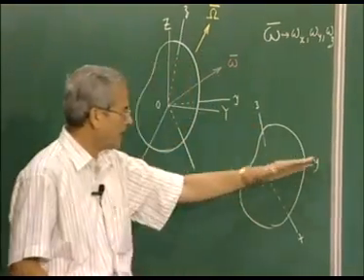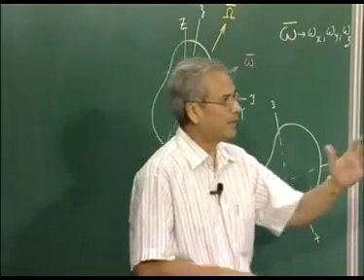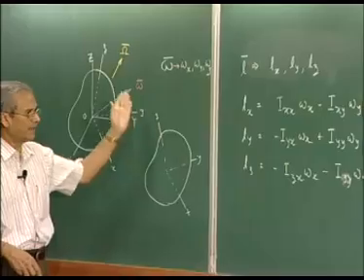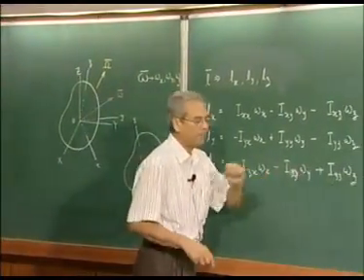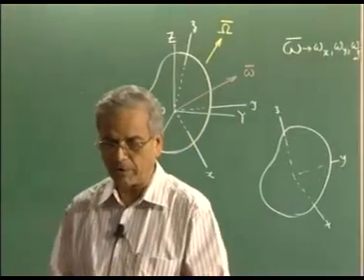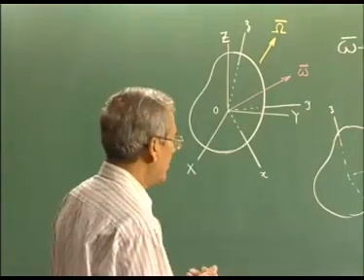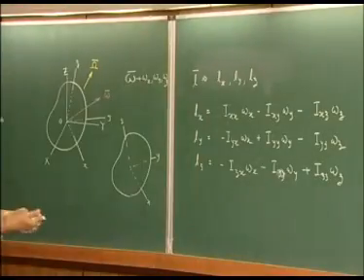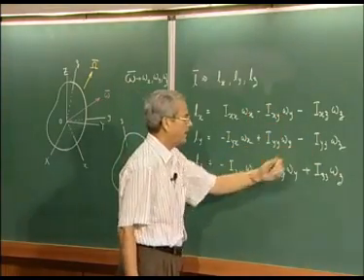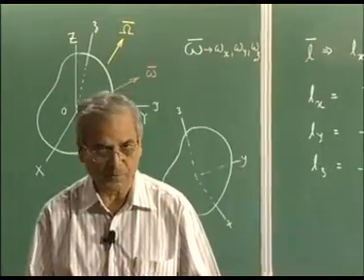The moment of inertia about a rotation about an axis y is Iyy, and moment of inertia for the rotation about axis z is Izz. So, these were familiar terms. We have seen the concept of moment of inertia even in plane motion of rigid bodies in our dynamical courses. However, these quantities Ixy, Ixz, Iyz are something new which you have not encountered before, and they are called the product of inertia.